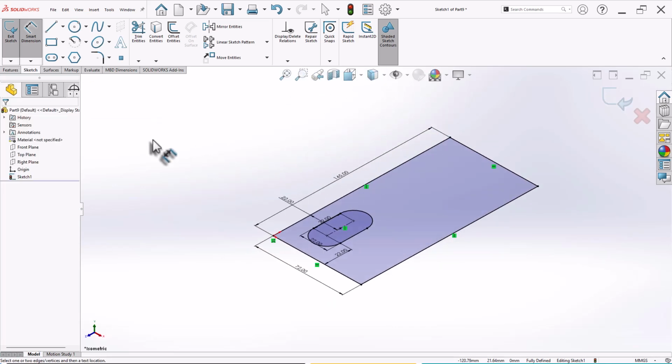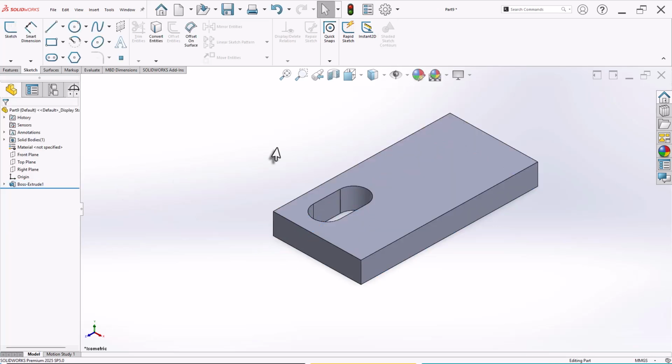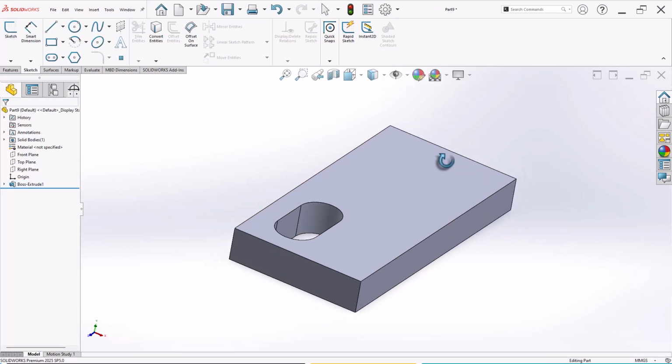Ctrl 7. Now press S key and select the extrude. Now distance is 18. Now here look very carefully. The distance 10 mm is already highlighted, so I don't have to go over there and enter the value. Instead I can straight away type the value and click enter. So bottom part is completed.